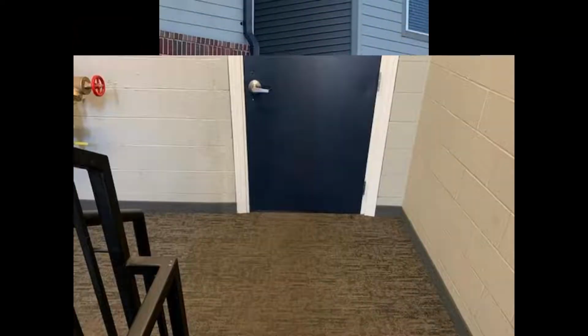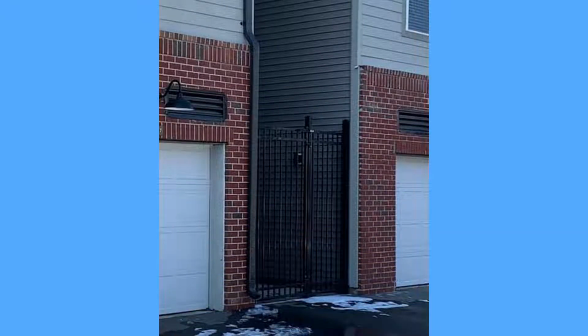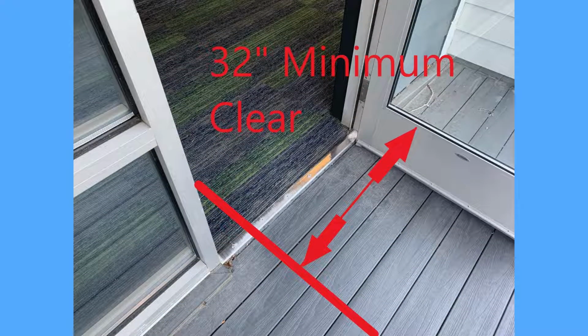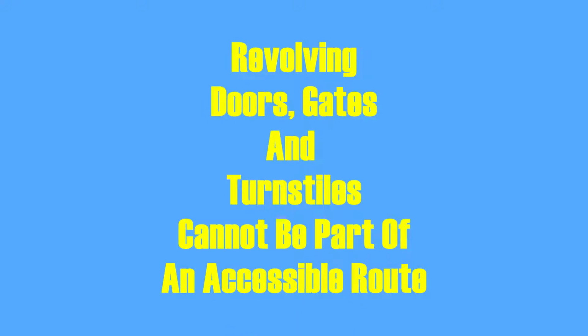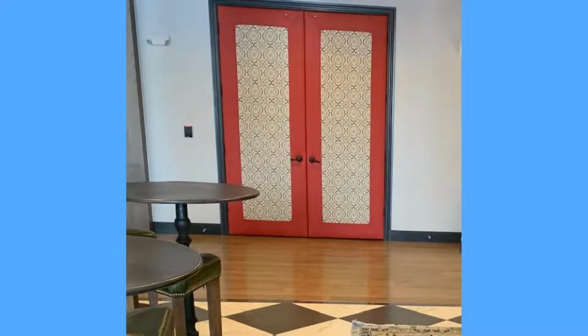Each door, doorway, or gate intended for passage on an accessible route shall provide a minimum 32 inches clear width. That width is measured from the face of the door to the doorstop when the door is opened to 90 degrees. Revolving doors, gates, and turnstiles shall not be part of an accessible route. Double leaf doors, at least one leaf, must comply with 32 inches clear minimum.